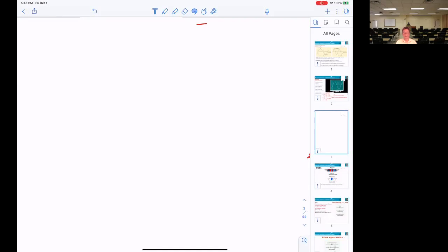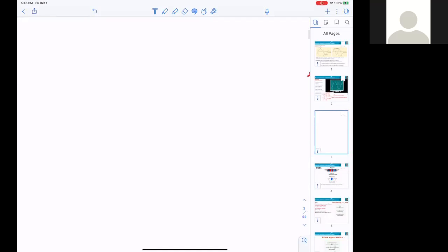That means you say you connect the DMM low side to the ground, high side to the output generator, right? Well, on some of those, they have an internal calibration where you can take channel 1 and hook it up to the ground post on the equipment and then do the internal software calibration. You're talking about calibration. Okay. But that's also monitoring. Correct me if I'm wrong. Isn't that verifying that 50 ohms? Yeah.